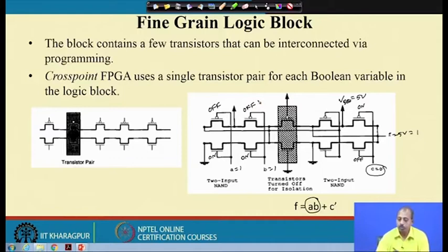Fine. So, what will happen? This point is grounded. So, this ground potential, ground voltage, is available here and through this line it will be coming. So, this line is made equal to 0 and you get a 0 voltage here. When this 0 comes, this is a p transistor with gate value 0, so this is turned on, and this is an n transistor with gate value 0, so this is turned off.